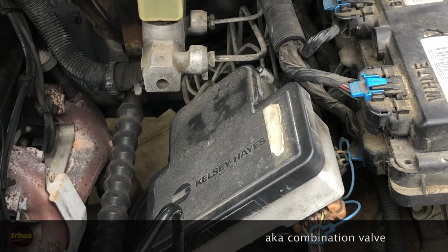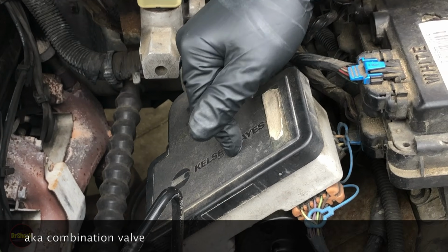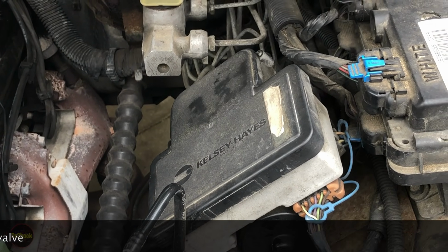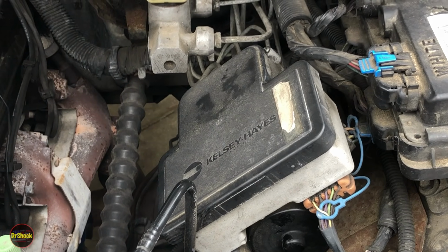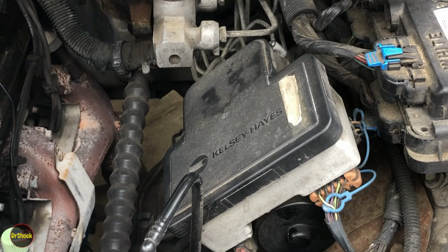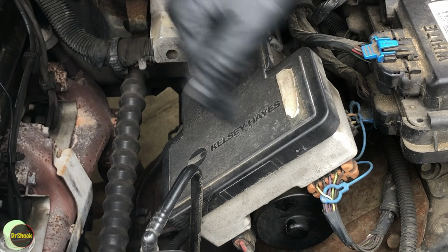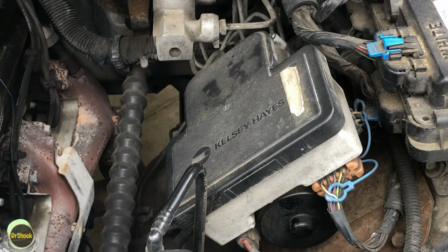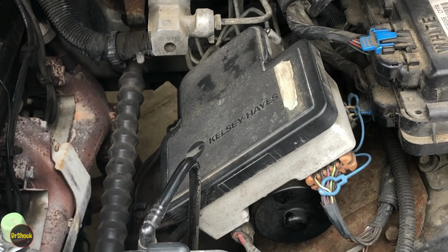These units are not common to all trucks. There are different EBCMs depending on the type of brakes your vehicle has. There are different BPMVs, and there are different proportioning valves. So even though they all cosmetically look alike, they are not alike. And that's why we took some information from the scan tool to know what's inside this EBCM in terms of its software date and version. But let's get started with diagnosing the problem.